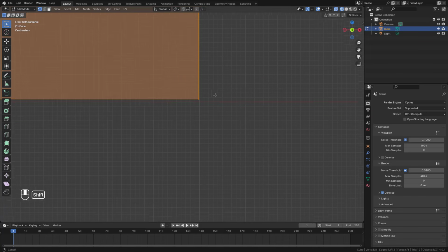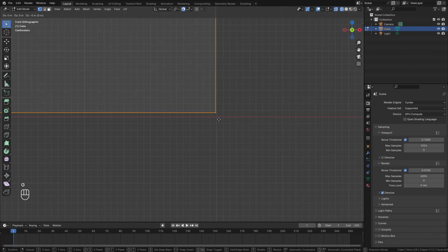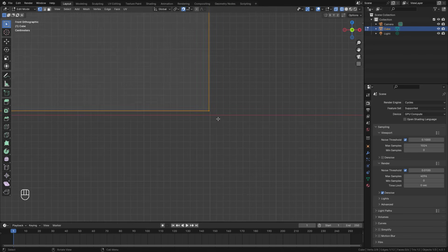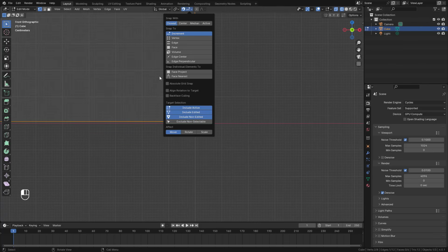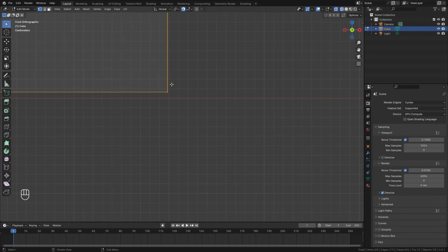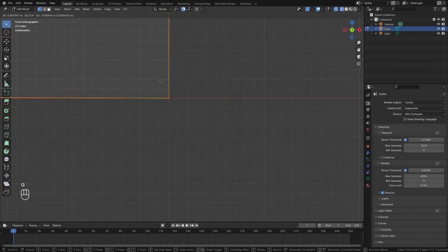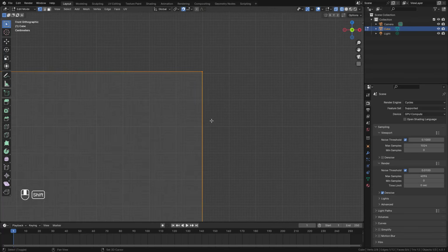So you can turn on snapping for this, turn on snapping and select these vertices and try to snap. But if you try, it doesn't want to snap exactly on this here, right? It doesn't want to snap. For this, you need to turn on one more thing, open snapping options and turn on absolute grid snapping. So now select these two vertices and come here. As you can see, it automatically snaps in the correct place.